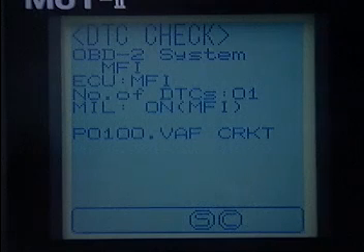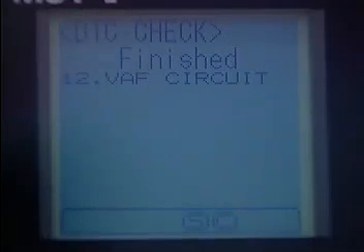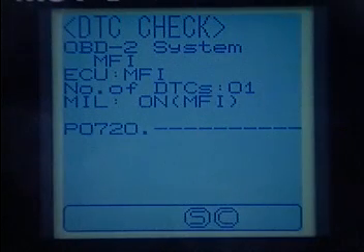For all 1997 models, OBD2 P-Series diagnostic trouble codes are displayed in both the GST and Scan Tool modes. These P codes replace the Mitsubishi diagnostic trouble codes that are displayed on earlier Mitsubishi models. And on the new Mirage, several new P codes have been added for engine and transaxle diagnosis. The number and types of codes vary depending on engine and transaxle combination.